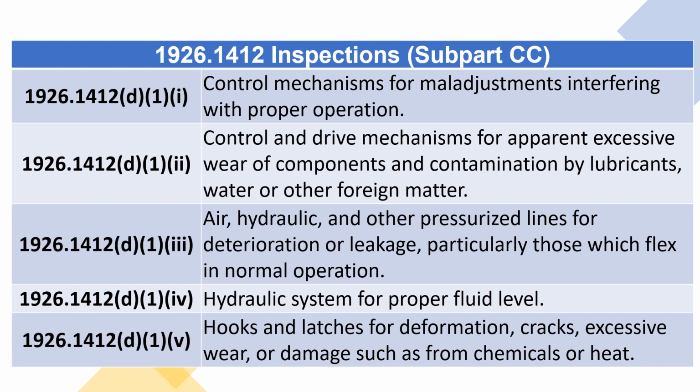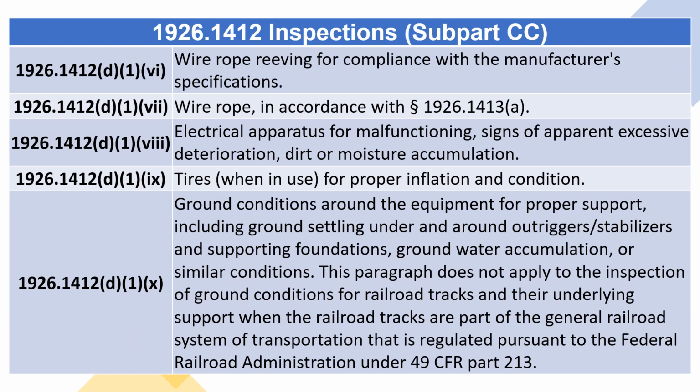Hooks and latches for deformation, cracks, excessive wear, or damage such as from chemicals or heat. Wire rope reeving for compliance with the manufacturer's specifications. Wire rope, in accordance with Section 1926.1413(a). Electrical apparatus for malfunctioning, signs of apparent excessive deterioration, dirt or moisture accumulation.